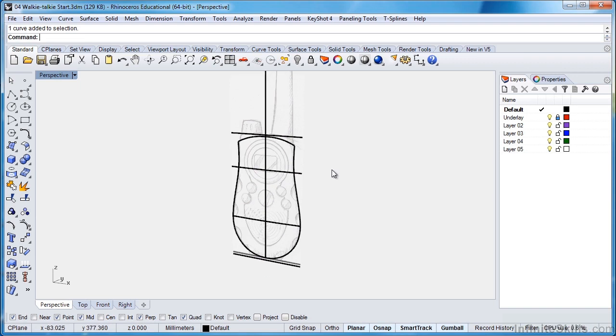And as fairly typical in Rhino or most 3D applications, we're going to actually overbuild our surface and then trim it back. You do this to make building surfaces much easier, and what I mean by that is it's much easier to build a surface with some shape through it going across a straight line and then coming back and trimming out this complex shape than it would be to draw cross-section curves through the shape and have that shape and these cross-section curves all build a form that is satisfactory. Not to say you can't do it. It's a little easier to do it this way.